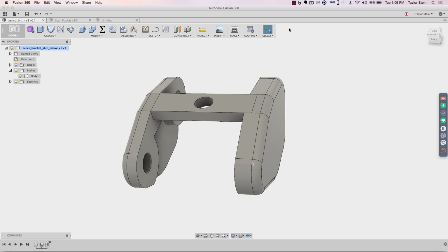Again, you can use Press Pull to move faces around, add fillets, and create new offsets. And additionally, you can turn the timeline on to start capturing the design features that you're using and create a workable parametric model. Now, a STEP file isn't the only type of CAD neutral file that you might be working with. There also is an IGES file, which is really a surface file that's really popular as well. So you might find yourself downloading an IGES file, and those work in a little bit of a different way.